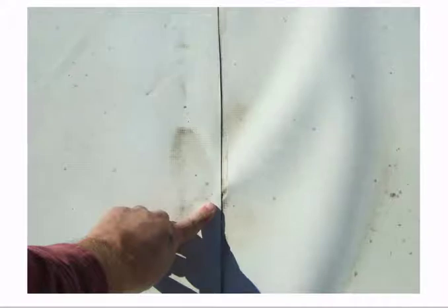Well, when ice and water get in there, over the seasons, it'll pop and expand and break that weld loose. So a standard contractor would come in and maybe try to weld that top membrane down into the wrinkle, or again, at worst, put a dot of caulk on that and walk away. The correct repair is to put what we call a T-patch over that, weld a patch over that.